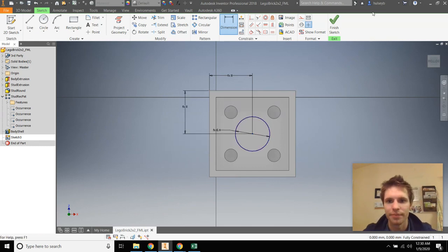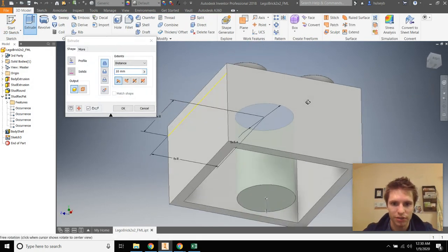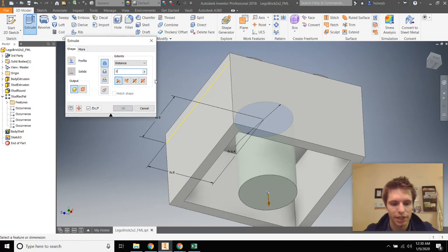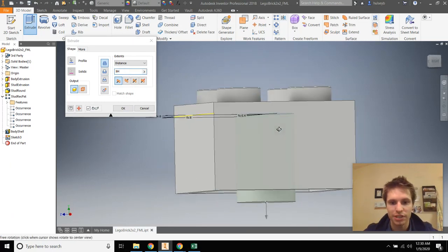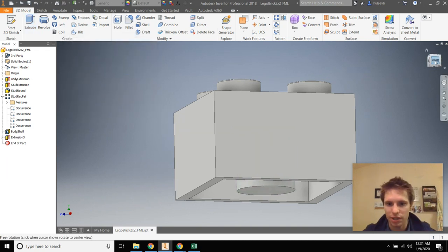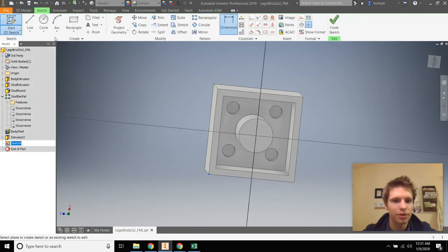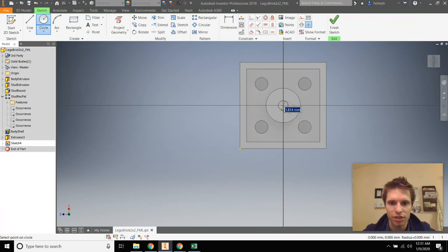Stud spacing entirely. So now we want to extrude this down, and the way we've got it right now, 10 millimeters, that's not right. We actually want it to be body height, but that's not right either. We need to take out the thickness. We need to subtract that 0.75. You can take out the body thickness, but I'm just going to do it the easier way for now instead of the smarter way. So I'm going to add a second extrusion as this whole cut. You could do 2 circles and extrude just the donut part. Doing it this way allows me to later time travel again and cut some of that rib stuff out. So I like it better this way.